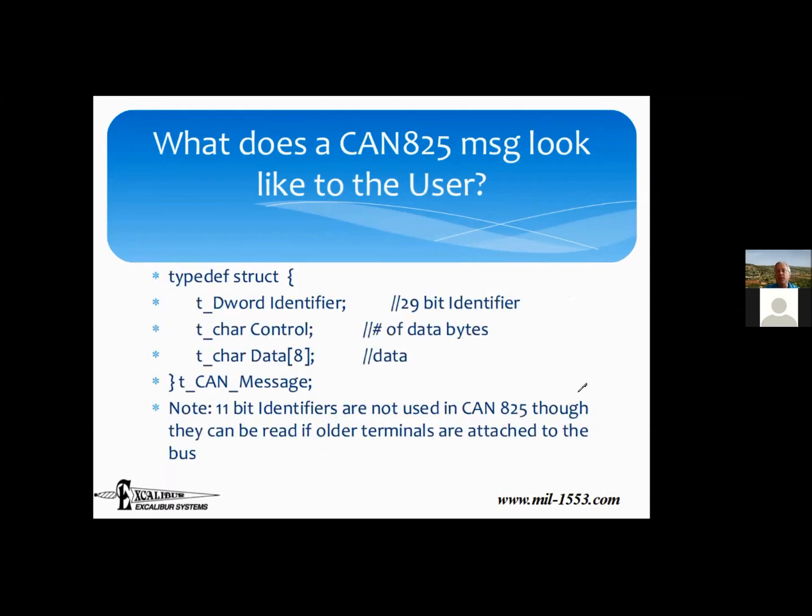Now, from a user's point of view, he doesn't care about most of these things. The user cares about three things: the identifier, the control, which is the number of bytes, and the actual bytes. Everything else is necessary for the hardware to know where's the beginning of a message, where's the end of a message, is it a legitimate message, or are there errors in it? But the user pretty much doesn't care about any of that.